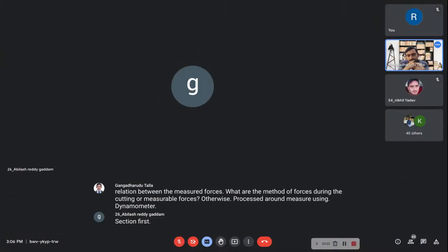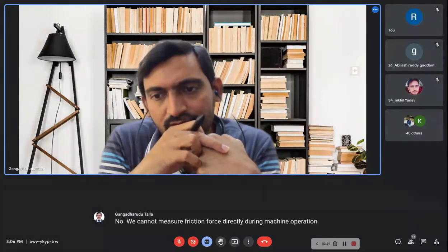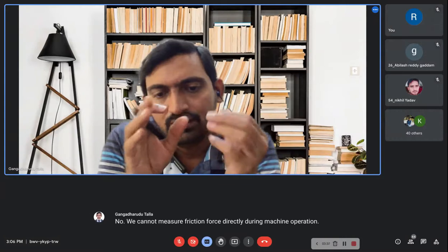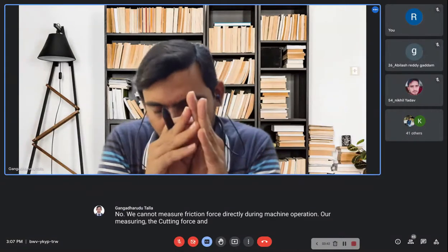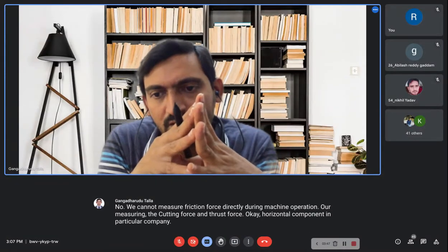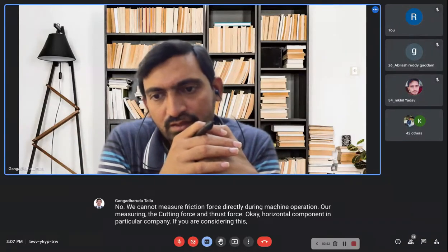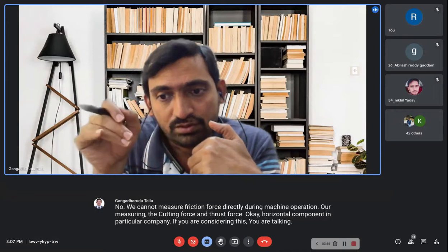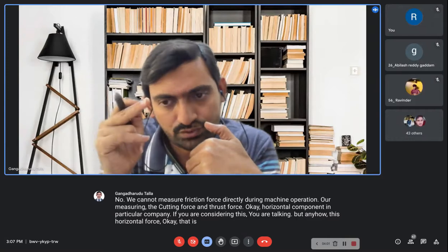Friction force. No. You cannot measure friction force directly during a machining operation. You are measuring the cutting force and thrust force, okay, horizontal component and vertical component, if you are considering pure orthogonal cutting.